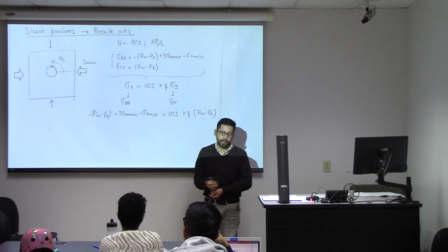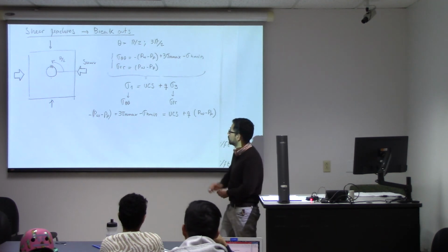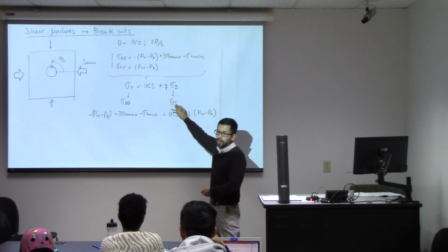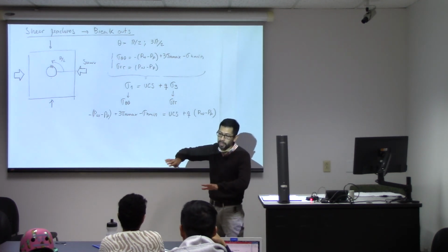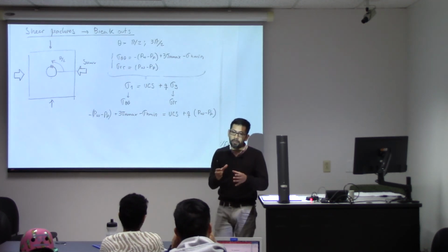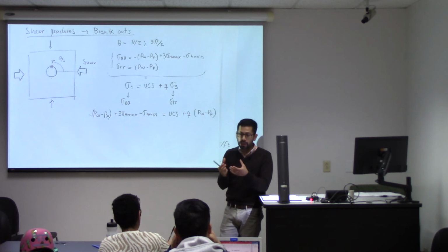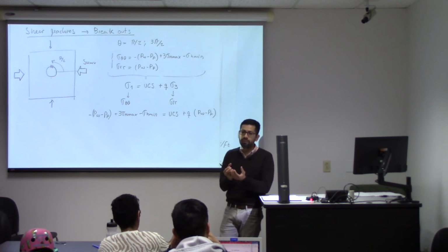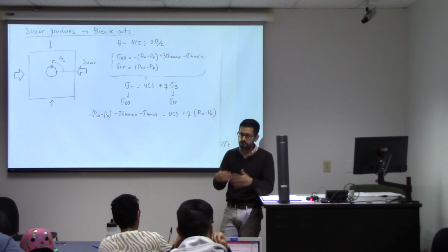So that's why in dry sands you cannot drill a wellbore, because you don't have any support from the sides, if you're not drilling with drilling mud. So the whole objective of the drilling mud is very similar to that membrane that we use for the coffee package, is to provide the support. So something that without the confining stress, it just breaks apart and flows.